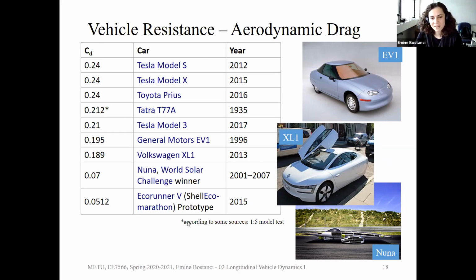But we have some winners in terms of aerodynamic drag. These are the solar cars, so it's going to move from that direction. As you see, it has very little frontal area, and the driver can see through that small space, and this is also closed. So it means that we need to decrease the aerodynamic drag as much as possible, but still we need to give drivers some window opening to see, and we need to make sure that the car is still drivable.